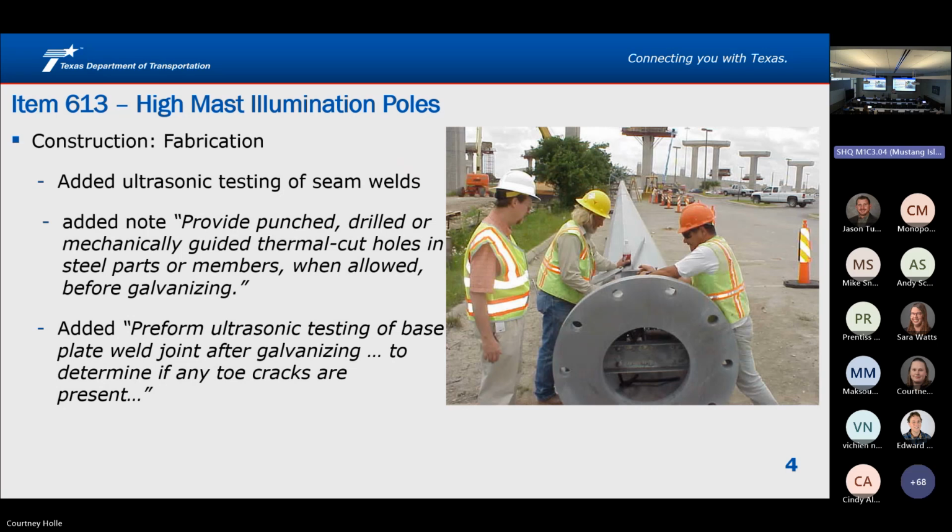Item 613, high mast illumination poles. In the fabrication section under construction, they added ultrasonic testing of seam welds. They added that same note that I just read earlier. And then added: perform ultrasonic testing of base plate weld joint after galvanizing to determine if any toe cracks are present.